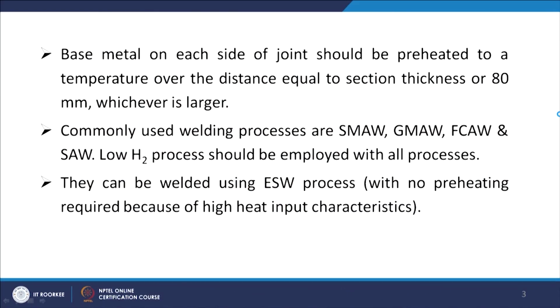Then in these cases the base metal on each side of the joint should be preheated to a temperature over a distance equal to the section thickness or 80 mm, whichever is larger. So, in these cases what we normally do is take care that on each side of the joint a minimum of 80 millimeter or the section thickness, that much must be preheated.